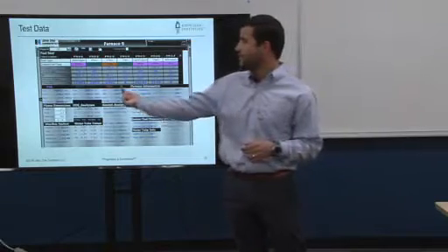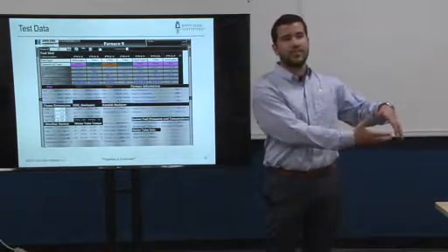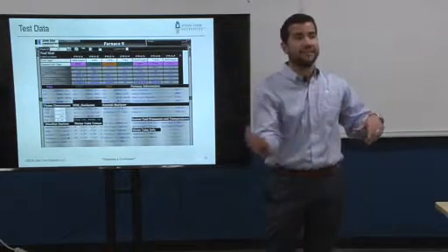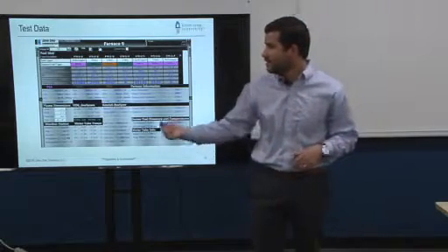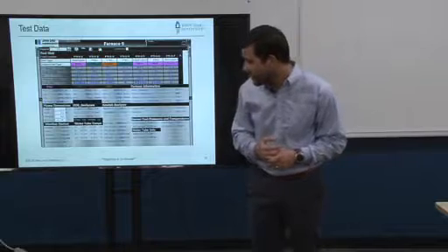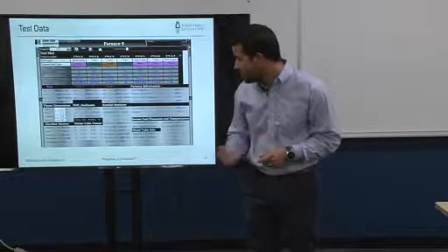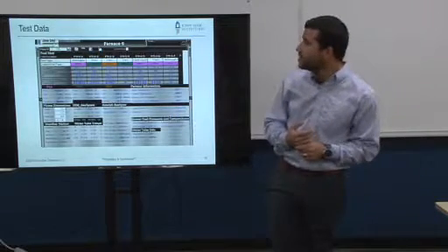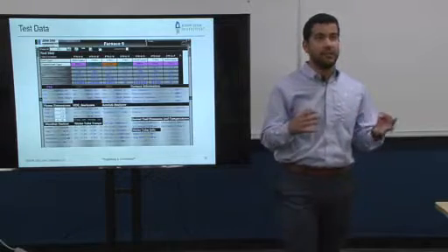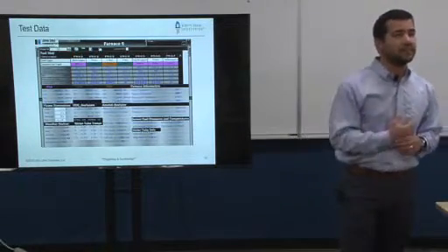And then I have the TEG burner. The way we simulate it is we have a separate burner on the side, and the flue gas or the combustion products of that burner is what gets fed to the main burner. I can tell that the TEG burner is firing about 8 million BTUs an hour, and it's providing a combustion temperature of about 963 degrees F. So in this particular case, I have 3 different fuel streams going to the 2 burners, and that's the way we monitor it.